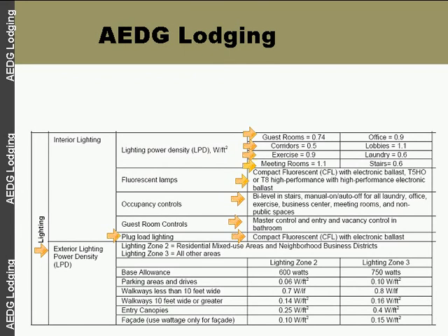For one, there's an adaptation issue: if I have a very dark environment and I brightly light an area, as I drive into it, my eyes will adapt to that higher, brighter level. When I then leave that environment to the street, my eyes take some time to adapt to that lower light level. And that's actually a safety issue. I might not see a deer or an object in the middle of the road. So if I can keep that light level more in tune with the environment that the buildings are in, I can save energy, and I also reduce the issues of light pollution and light trespass.